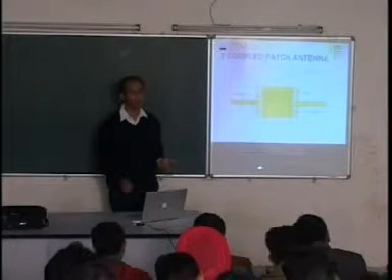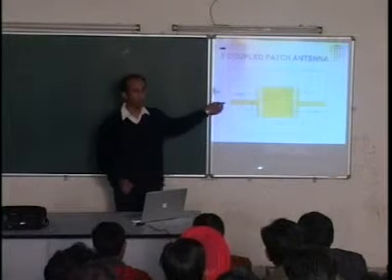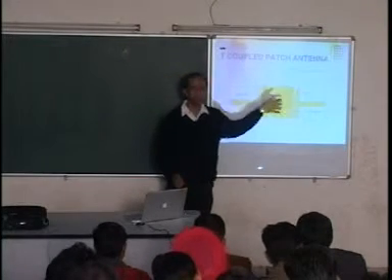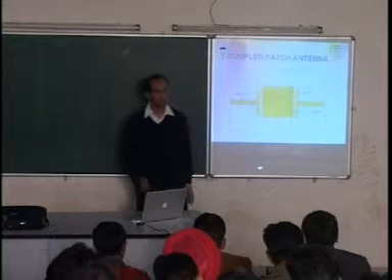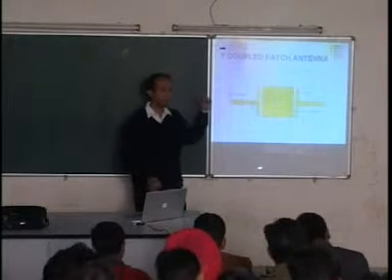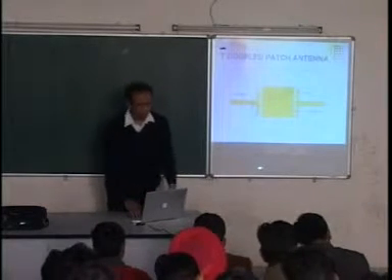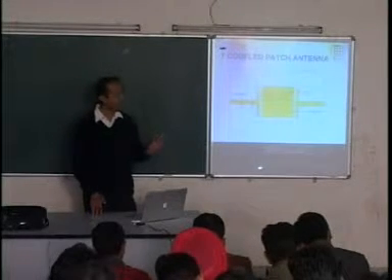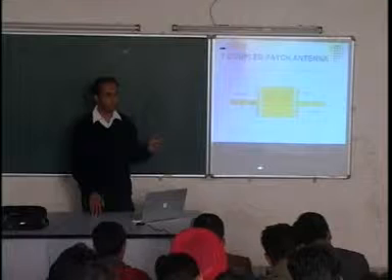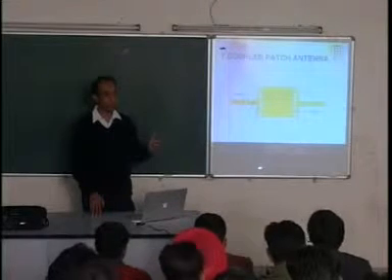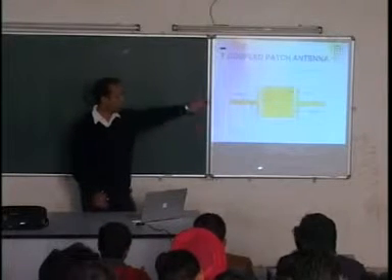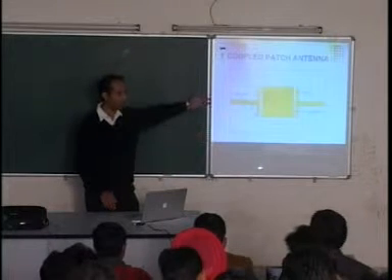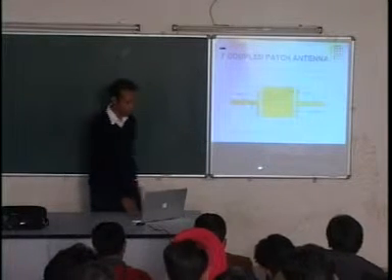So this is what it is. At 5.5 gigahertz, this will transmit half the power, radiate half the power. At other frequencies, whatever comes in goes. Ideally. In reality, it's not like that. All resonators have loss. Nothing is perfect. In fact, the loss is quite high. 30 to 40% of the power will be lost actually at these frequencies.